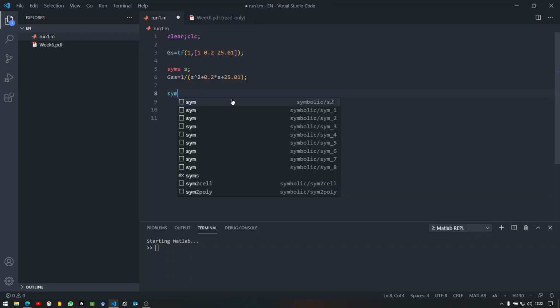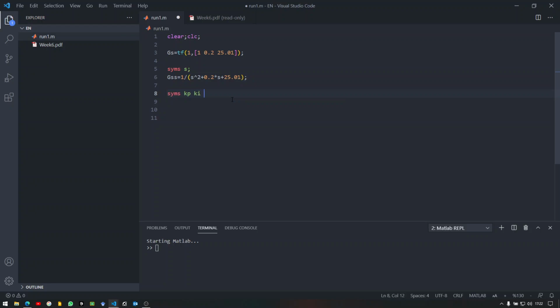So, now, we've talked about this before, but let me remind you that if you are going to use the algebraic method, where we use the polynomial coefficients and their equality in order to get a solution or a design for the PID controller, then almost always you should go ahead and use the kp, ki, and kd parameters instead of zeros and the gain.